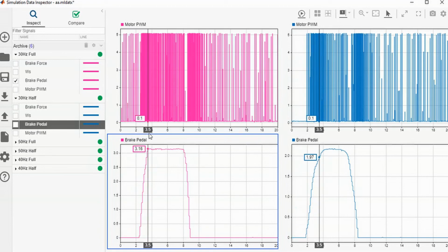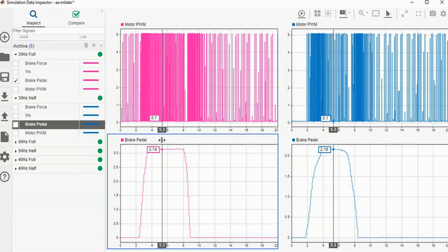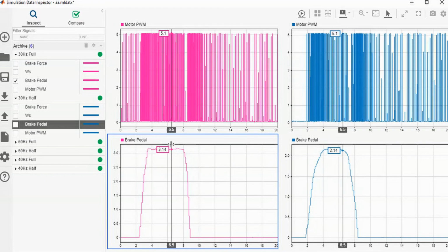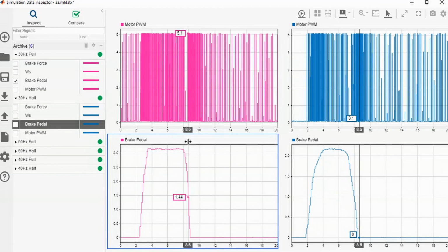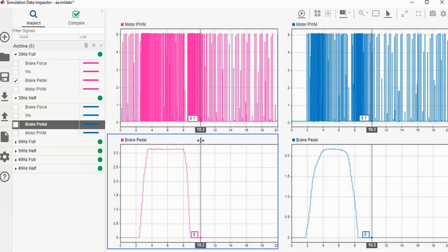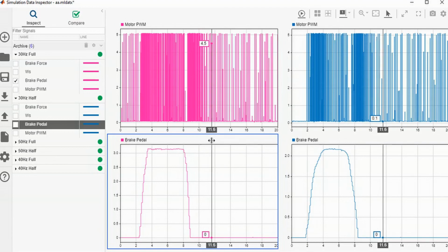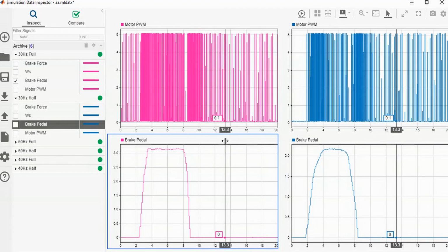At the hold position, the PWM value remains the same to hold the braking position so the wheel can stop moving. After the brake pedal is released, the PWM value is increased so the encoder can reach the assigned position faster. But before it reaches the assigned position, the motor will slow down so it can stop at the exact assigned position. And the rest, the value of the PWM will remain the same.